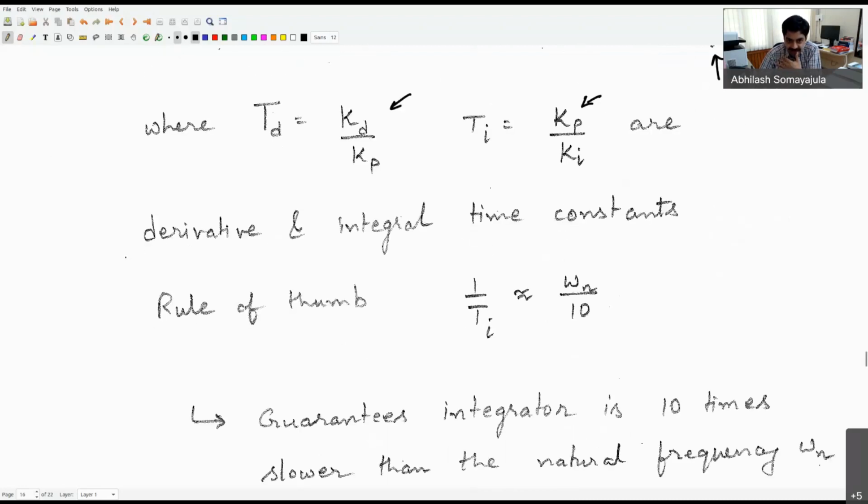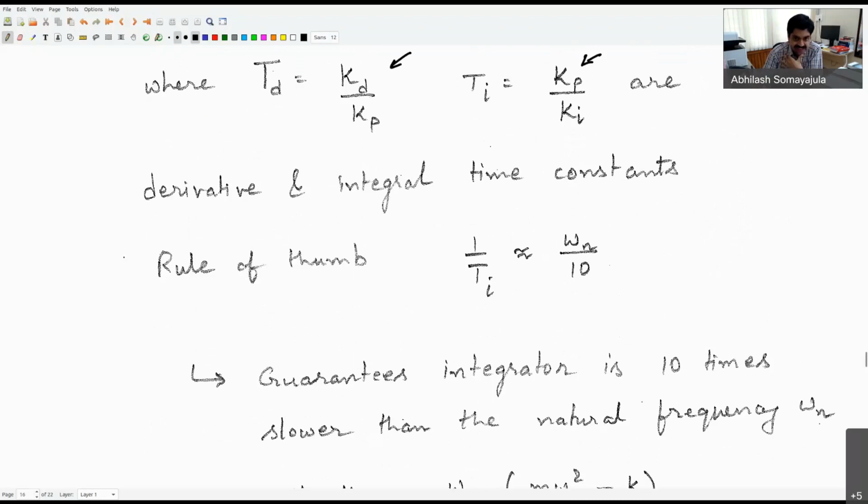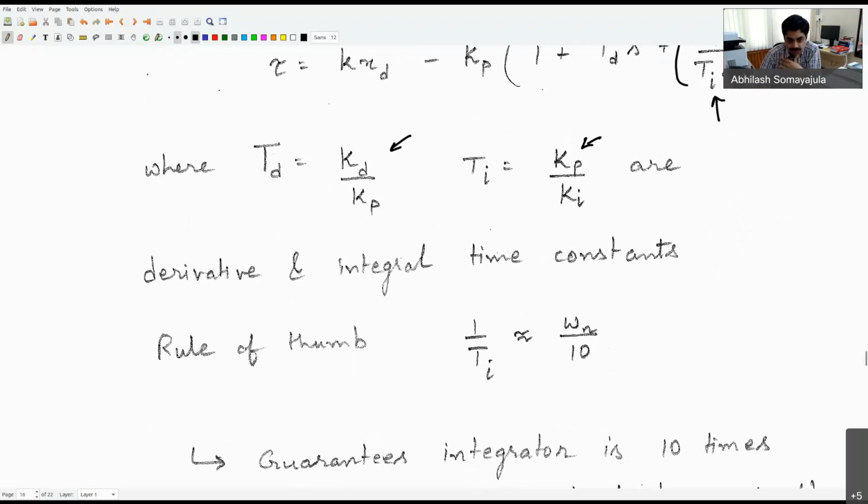All right. Now, when you typically look at a rule of thumb, as I said, this integral gain you want to keep pretty slow. You don't want that integral gain to be very big, because it is basically integrating the error over time, right? As time increases, that integral term, the integral from 0 to t of the error, will also keep increasing. And therefore, it can start having a very wonky behavior. It can lead to very large overshoots in your system, which means that if I ask it to track a 10 degree heading angle, it may go all the way up to 30 degrees before it comes back down and stabilizes at 10 degrees. So this integral term, we want to make sure that it's not varying very quickly. So this coefficient Ki, we want to keep as low as possible typically.